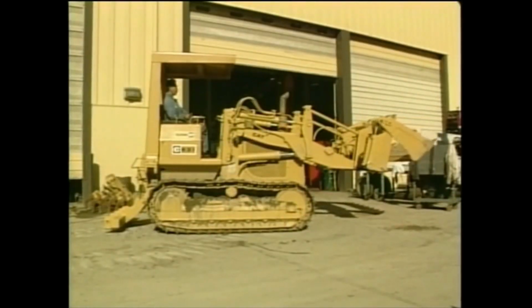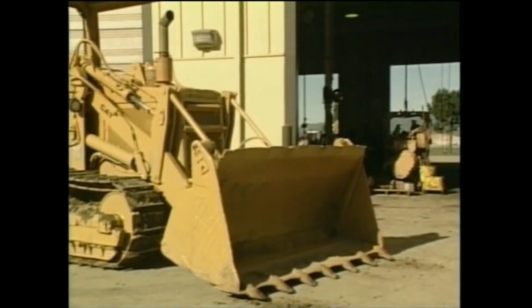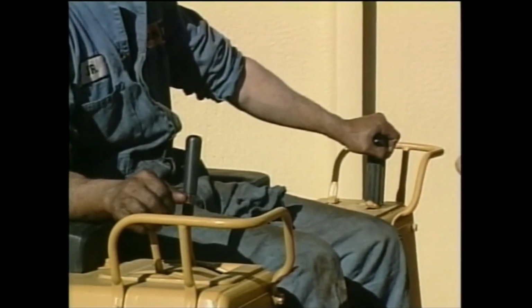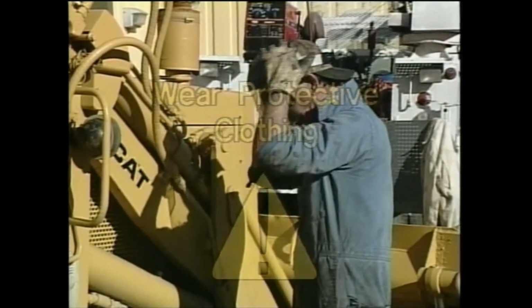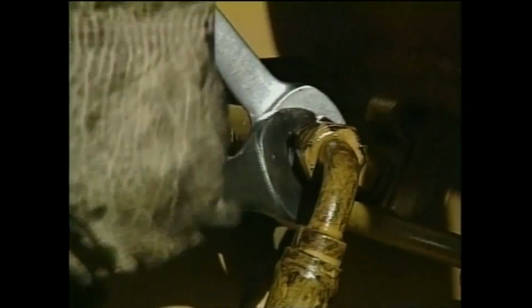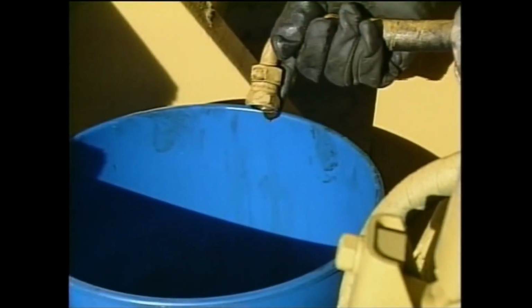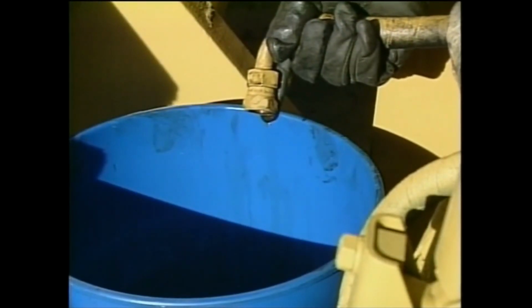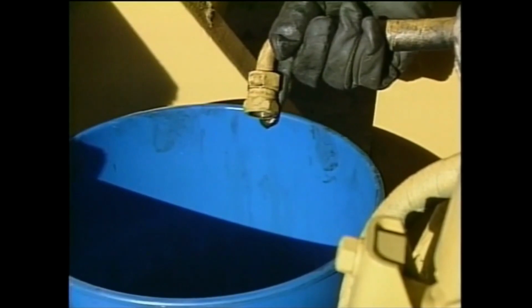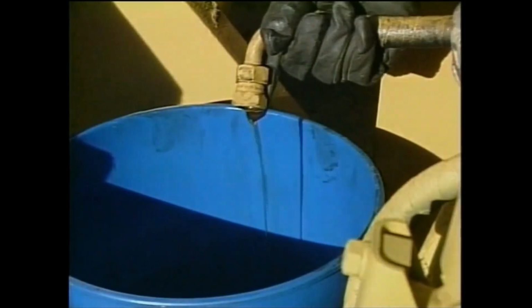Extend or retract the piston in the cylinder to be tested. Lower the mechanism to the ground. Shut down the engine and neutralize the hydraulics. Put on an approved face shield and gloves to protect you from hot oil. Remove the hose from the end of the cylinder where the piston is resting. Place the hose in a bucket to collect the oil. Then, pressurize the cylinder for 20 seconds at maximum governed RPM and watch to see if oil is leaking past the piston seals and into the bucket. Excessive leakage will slow down the response time and reduce the power of the cylinder.